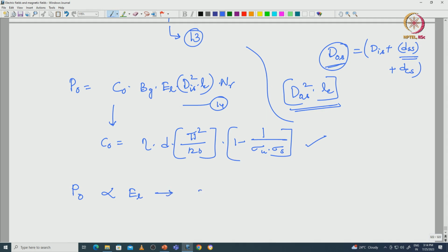We have to select the electric loading appropriately in the range of 25,000 to 90,000 ampere-turns per meter, because each phase generates torque individually. At a time only one phase is excited, so for that reason we have to select a higher electric loading, or current carrying capability of the winding, in order to generate more torque.